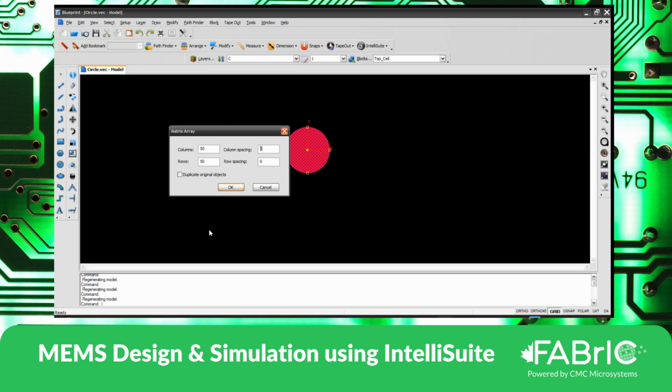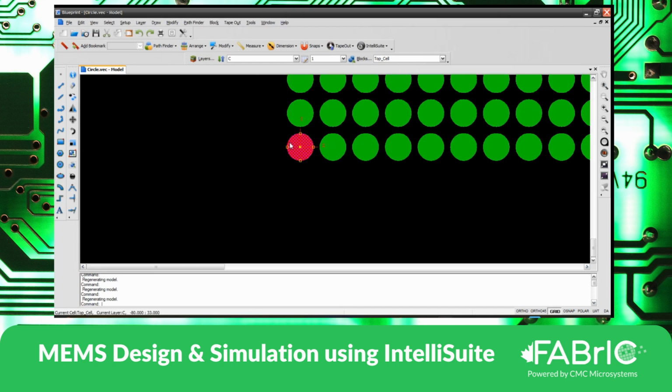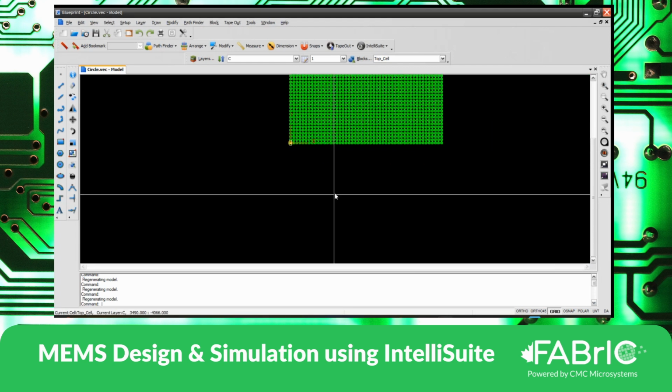So column spacing can be 250 micrometers, because I would consider from the starting point 200 micrometers covers the diameter of the geometry, and another 50 is for the dicing area. Then in the x and y direction I have this set, then click OK. So now I have so many geometries.